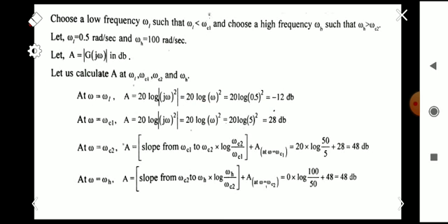And on the y-axis, we know that the maximum and minimum values are 48 and -12. So we have to choose 50 decibel as the maximum and -10 as the lowest. Likewise we can select the scale here. The topmost line is 50, and the next dark line is 40, then 30, 20, 10, 0, then -10, -20. We have to choose up to -20 because we have to mark the points -12 and 48, so those points can be accommodated between -20 and 50.